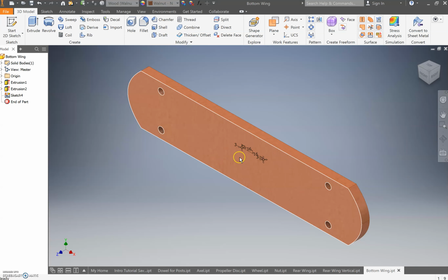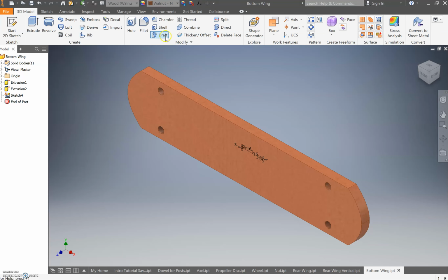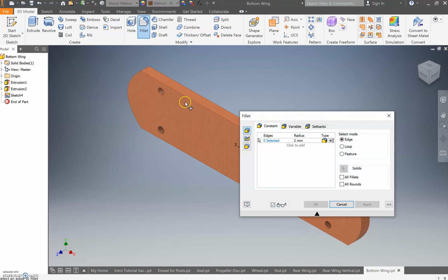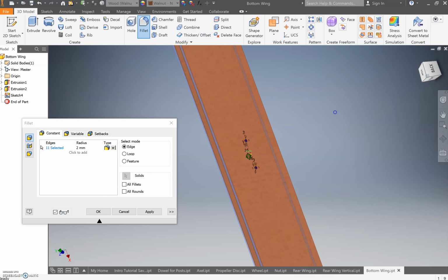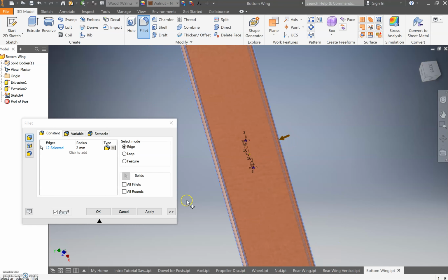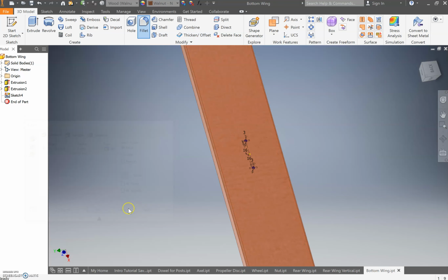From there, you've got this and it looks great. Something we forgot to do in the last one was add a lovely fillet to all of the edges. So we're going to do that now, and we're just going with a 2mm fillet. It's soft, it's kind, and you can get carried away fairly easily by adding fillets. As you can see, I'm going around, adding it to both edges, and you can move these boxes around so you can see better on the top and bottom. I can't get access to the bottom one, so I'm going to flip this over and select that as well. Then press OK. Then press Save, so you can press Control S, click the Save button there, or you can come in and go Save.